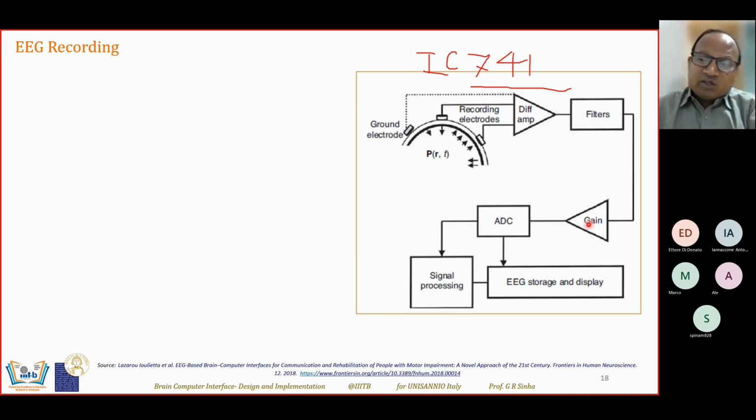So you can again pass it through a gain or amplifying device. If required, you can pass it through the ADC. After getting the signal, making it proper, filtering it, removing unwanted signal, you can finally convert it into digital. You cannot directly convert into digital here because the unwanted signal will also be unnecessarily converted. Then you are spending extra cost on the hardware and your timing will also be more.